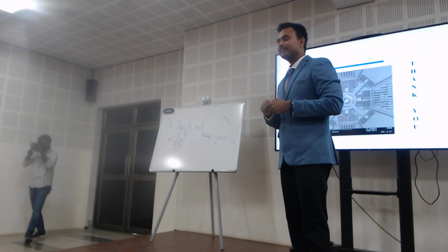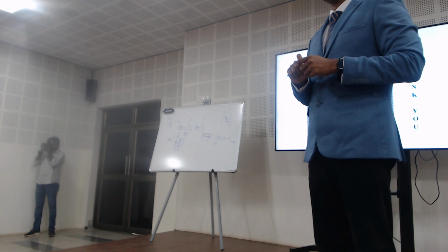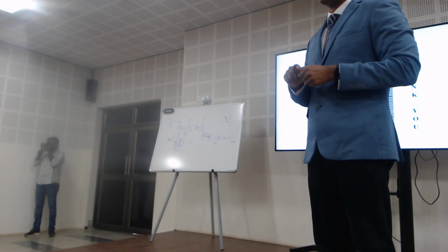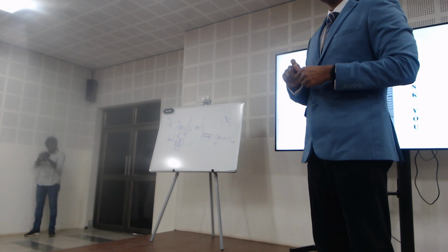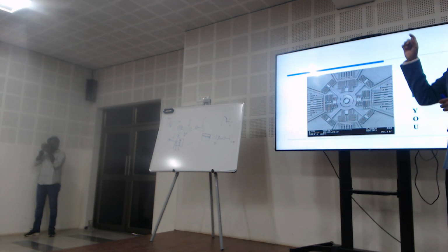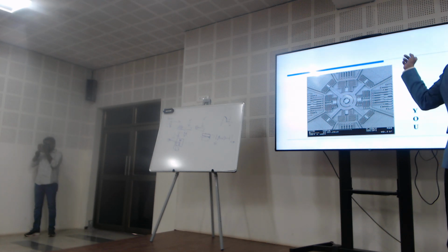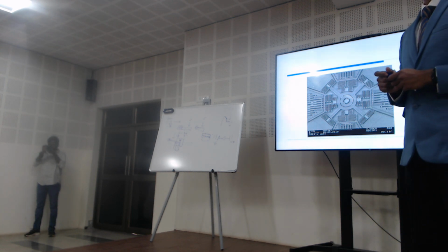The fabrication uses only the lithographic process, right? Lithography, e-beam, electron beam. I thought it was photolithography. No. If I do photolithography now, I get 6 micron, and maybe I will get 2 to 3 micron only. So e-beam is very accurate.